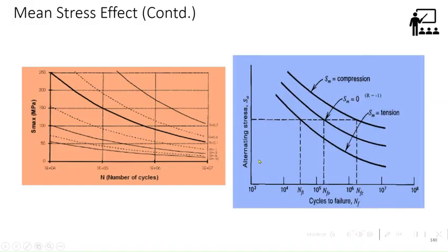But what we saw in the previous slide is the range. Your S max, stress range and R are interrelated. To explain, on one hand you are telling R is increasing, your detrimental effect, your life is decreasing, but here you are getting an increase because you are referring to the graph of S max, not to the stress amplitude.